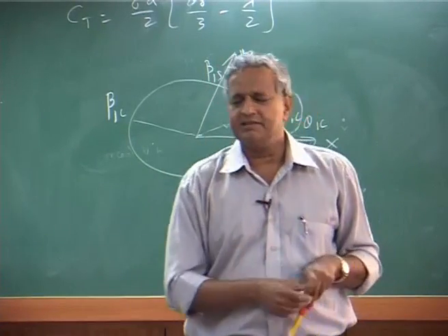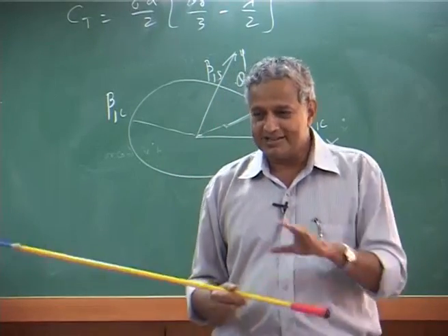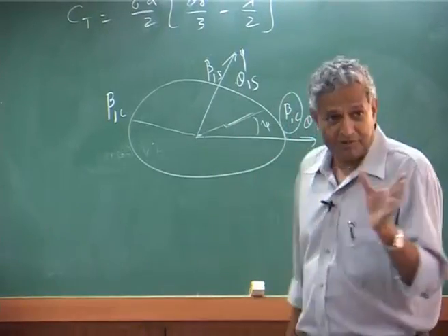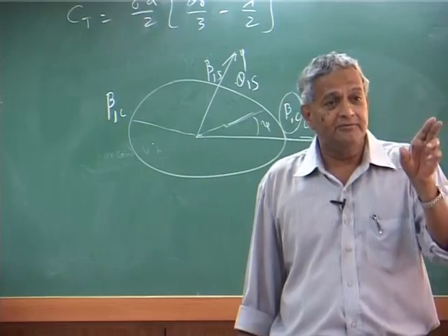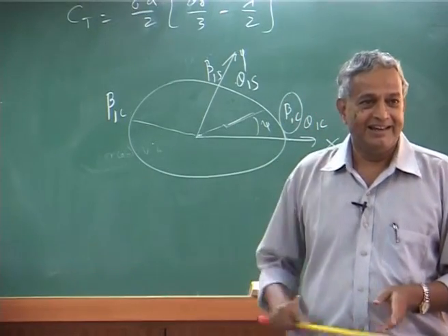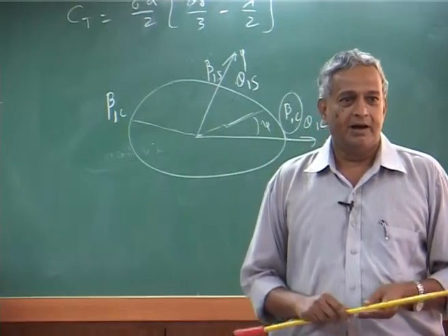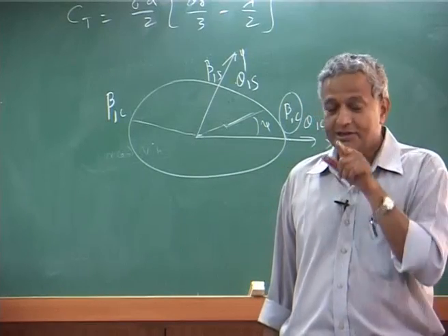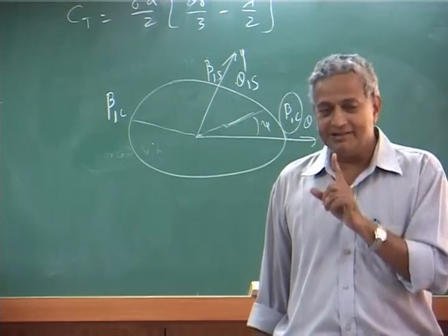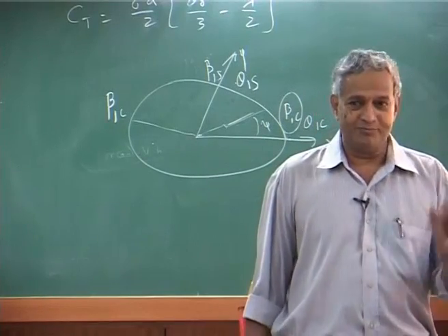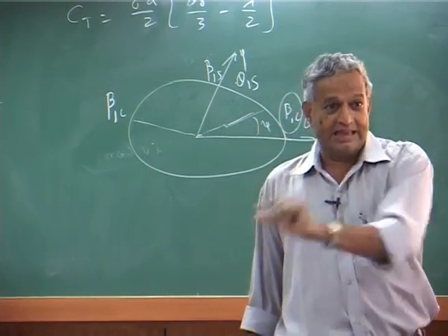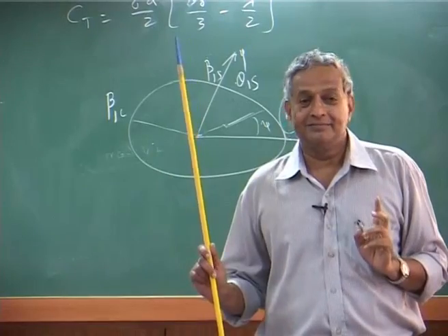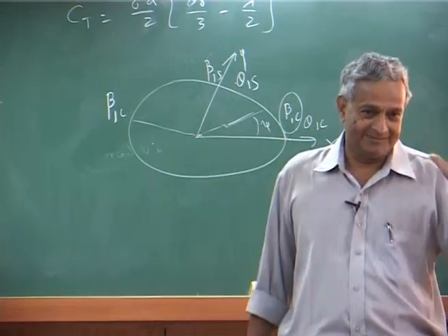The 90 phase shift comes because it is at resonance, because if you have studied a little bit more carefully your vibration part of the m x double dot problem, how the phase varies with frequency, all the phase curves, no matter what damping you have, will cross at omega over omega n equal to 1, they will cross at 90. That means, when the input frequency is equal to the natural frequency, the phase difference between input and output is 90 degree.